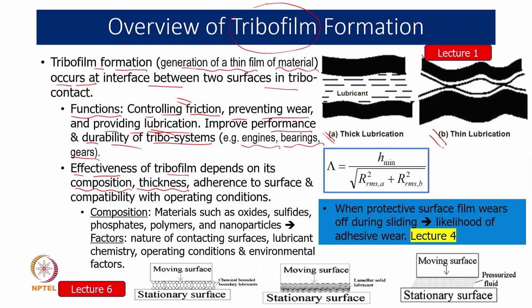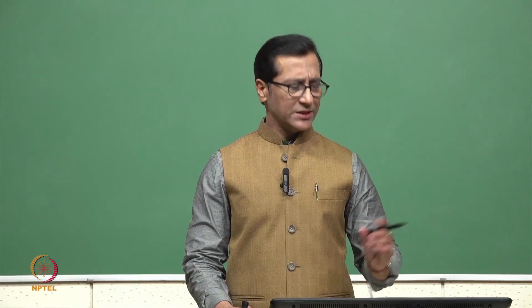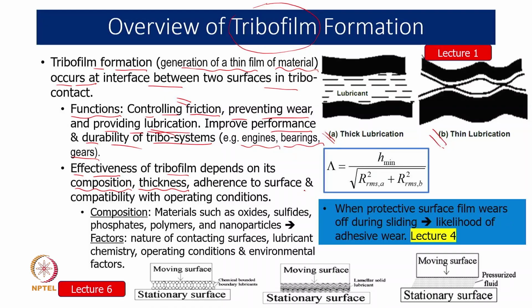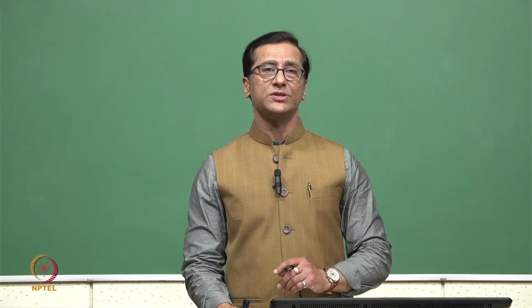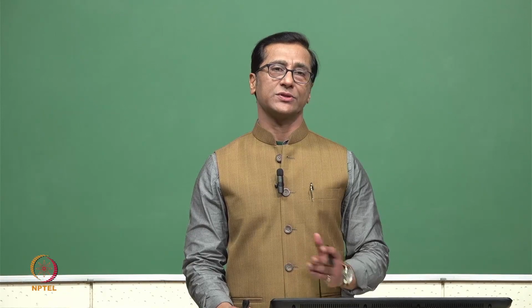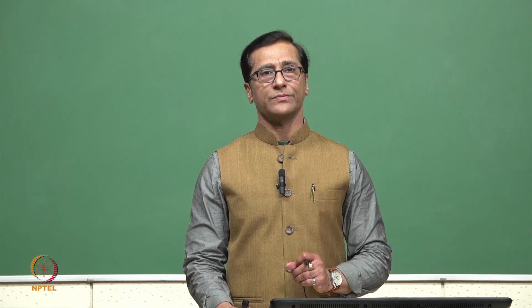Earlier we were talking about thick lubricant layers or tribofilms, but now we are talking more or less about thin lubricant layers. What will be the adherence of this tribofilm to the surfaces, and what will be the compatibility with the operating condition? If it doesn't remain on the surface and gets removed during shearing or sliding action, then the tribofilm is not effective.